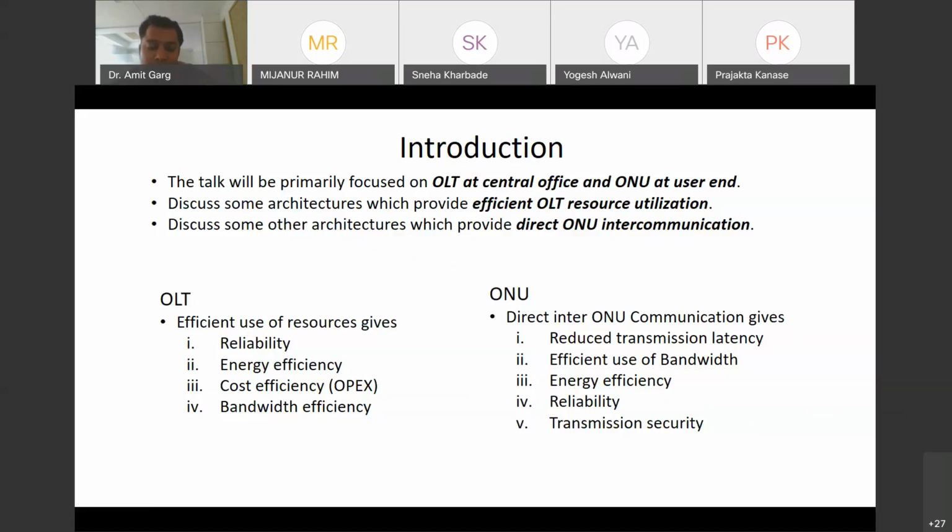For that idle case, when the network does not have active users, we can definitely turn off the particular TRX or transmitter to save the energy. These transmitters are fitted into racks or slots, and that slot also consumes power because we need to give the power to that rack or slot.